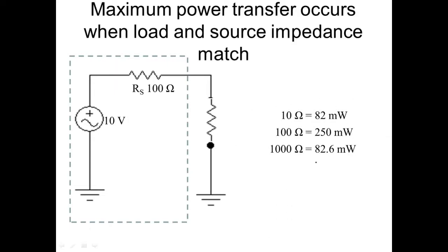What's important is when the resistance of the load matches the resistance of the source. So we don't arbitrarily let that happen; we set the communication of the system. If I use 300 ohm cable and I have a 300 ohm output on my amplifier and a 300 ohm input on my receiver, then we get the maximum power transfer I can possibly get in that system when the impedance matches.